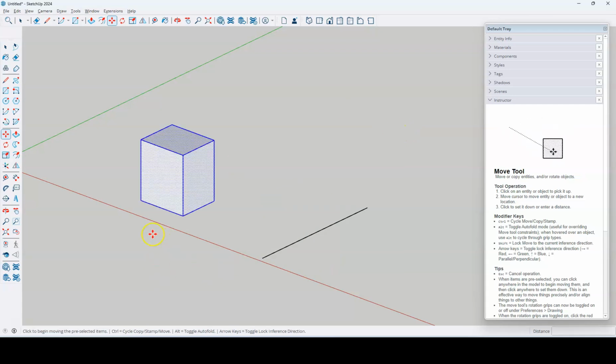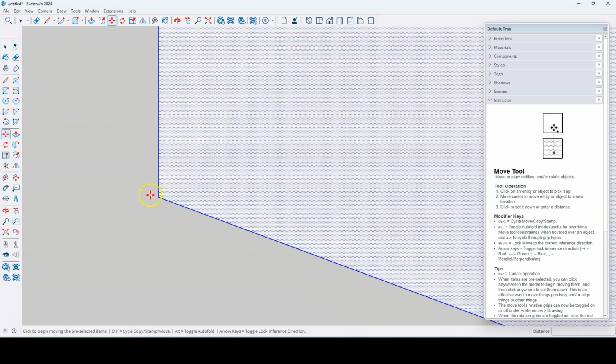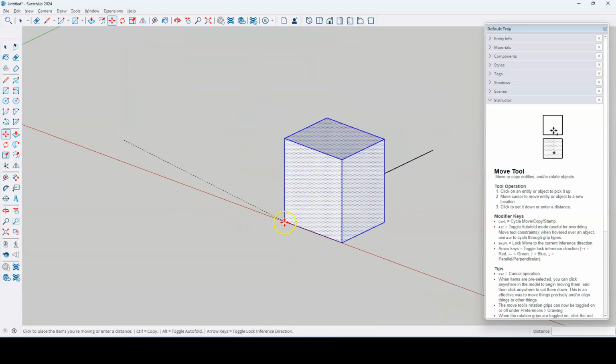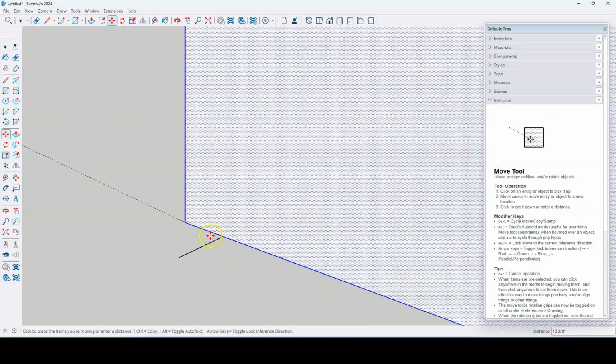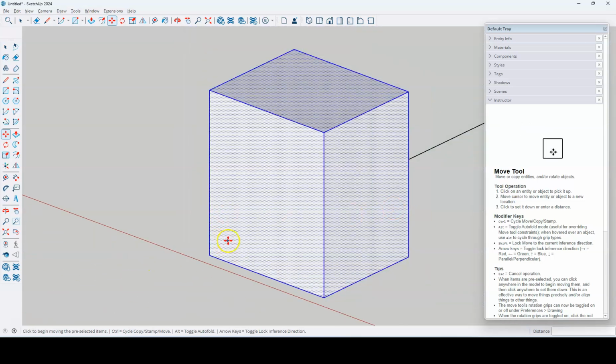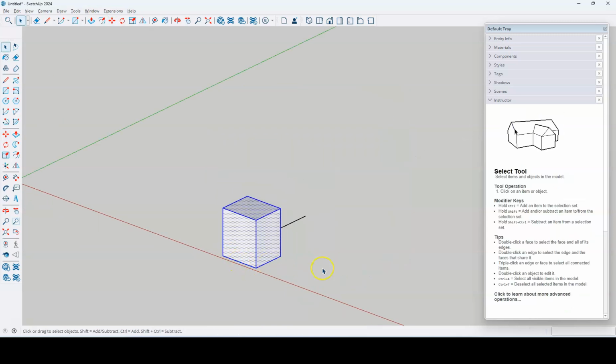So if you're trying to move it very exactly, I would go in there, grab that corner, it showed up green, SketchUp's telling me, yes, I have the end point. I click it, and I'm just clicking, I'm not dragging, and then I can come over to this point. Again, SketchUp will snap, telling me when I found the end point, and then I can click to finish it, and now I know that it is exactly at the point that I want it to be. If you don't care where it's moving to, by all means, grab some random place on the workspace, but typically, you want it to be pretty exact.